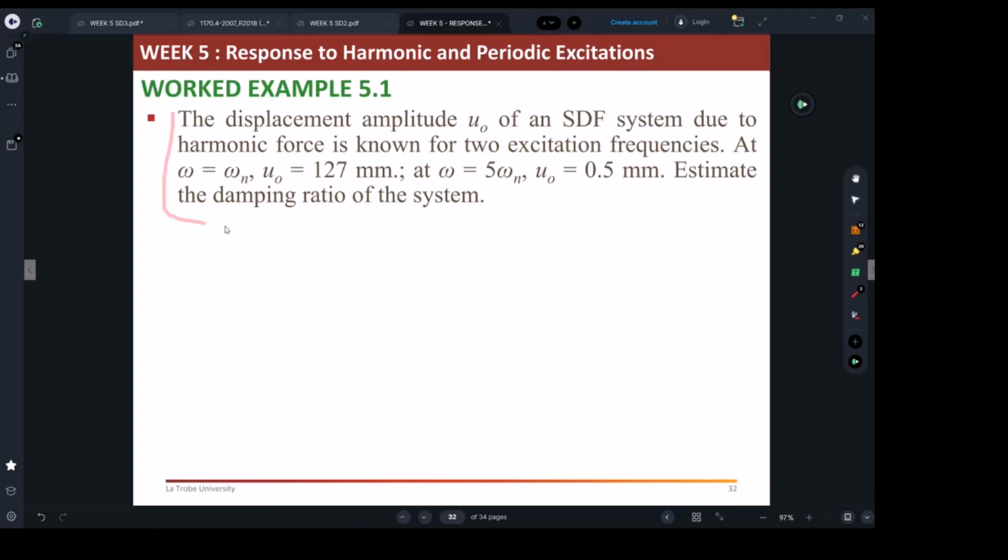So this is again an example where you may be required to determine the damping ratio, the eta, for a system. You're going to take a machine that will be applying frequencies to a system. From calculations, you will be able to determine the natural frequency of the structure, because you're going to know the mass and the stiffness, and from these two you can determine the natural frequency.